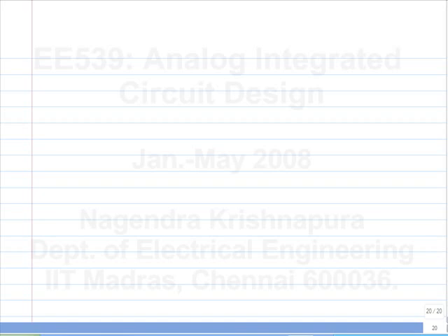So basically, see this circuit, some of you at least may come across this, is to make this using discrete op amps. Especially if you go into photonics and so on, you will get exactly the same circuit. You will have a photodiode and you will have to convert the photodiode current into a voltage and then do further processing. And as usual, the goals will be to do it with as little noise addition as possible, and get as much gain as possible. The two are somewhat related, and also to get as much bandwidth as possible. That may be another criteria.